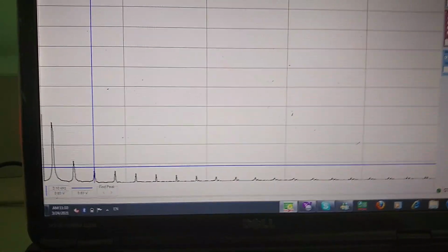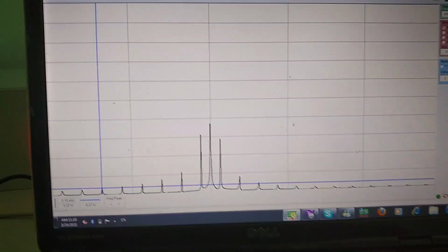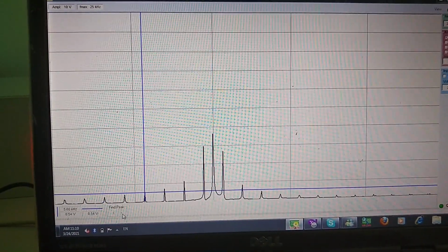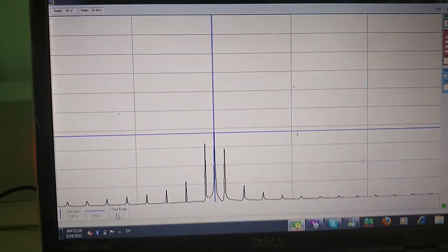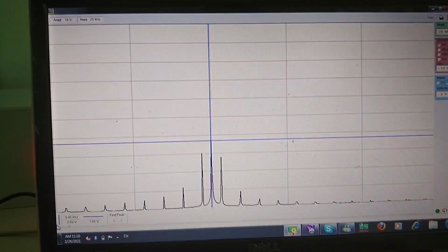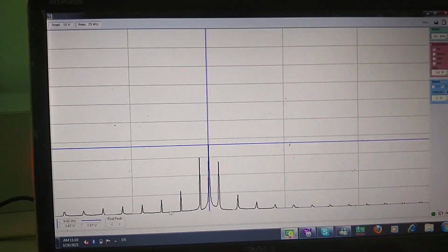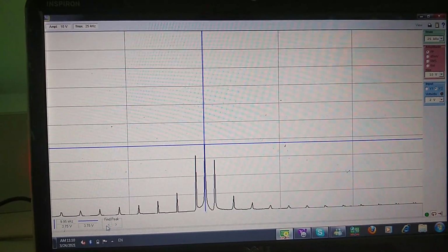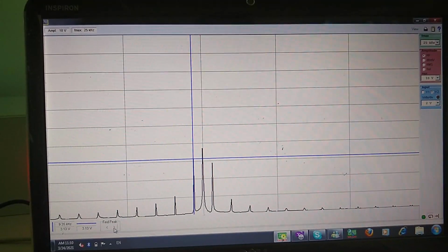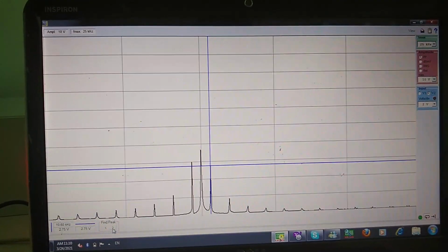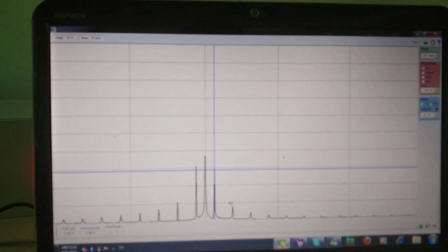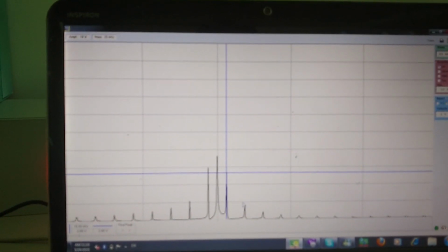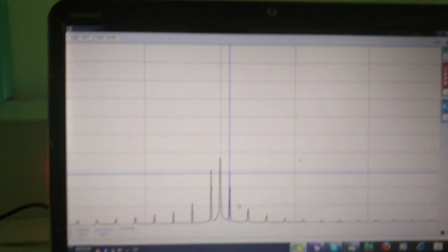It is the modulated ASK waveform. The modulated ASK waveform is in the center. You can find here it is 9.95 kilohertz, and here it will be 9.35 and 10.6. Okay, you can draw just these 3. This is the modulated waveform spectrum.